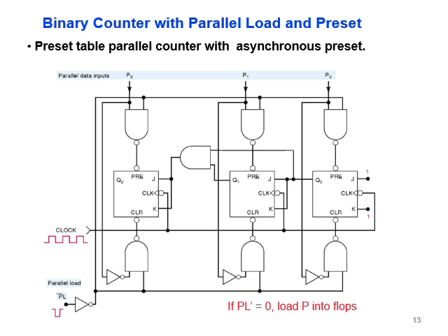And here we have a binary counter with parallel load and preset. As you can see here, we added PL, which is parallel load, which is either 1 or 0. The same idea as the previous one. You can see here, I call them P0, P1, P2, and so on. These are the parallel load. But the issue here, if PL dash is 0 here, then 1 will be here, then you can load input. Okay, we make this, let me say, a button to make sure either you let P input or you stop P from becoming input.